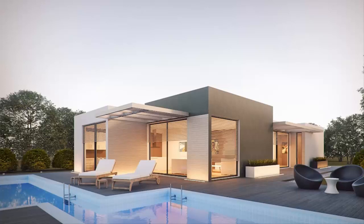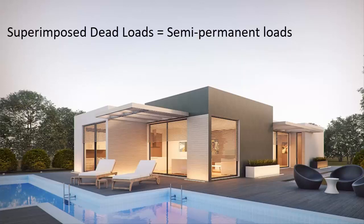There's a subclass of dead loads called superimposed dead loads, which are semi-permanent loads that are not part of the structure itself. In this house, the superimposed dead loads can include the carpet, the floorings, light fixtures, the bath and vanities, cupboards, kitchen, the air conditioner or heater. These loads are fixed to the house but can be removed, so are not permanent.